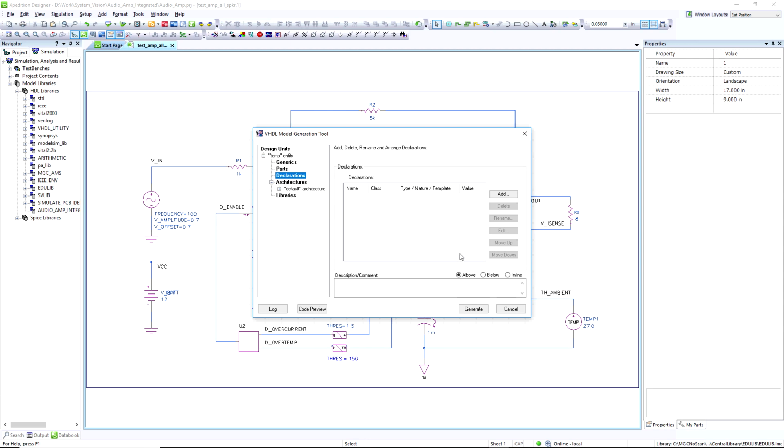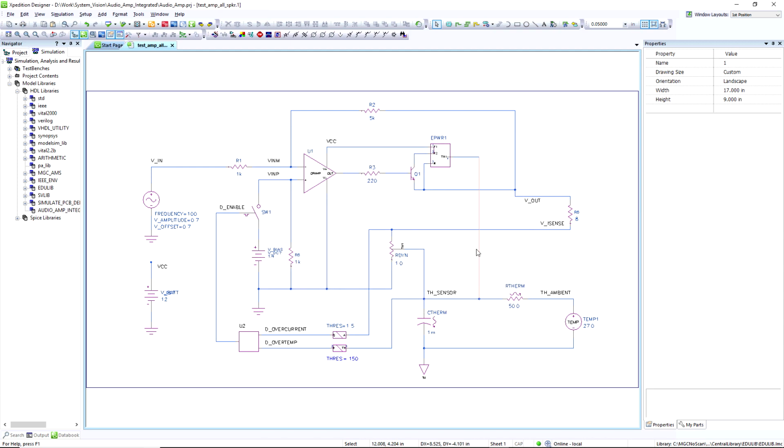You just have to give some guidance on what's going on. Maybe you just want to grab an existing VHDL-AMS model and work off of that. At the high end of the Xpedition AMS package, you can integrate with ModelSim and have large VHDL or Verilog blocks that you're simulating. ModelSim would obviously speed up the simulation on that end. Or you can also link up to tools like MATLAB and have part of the simulation running in MATLAB while the circuit itself is running back here in AMS.